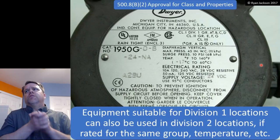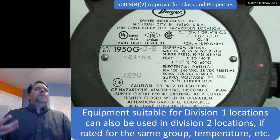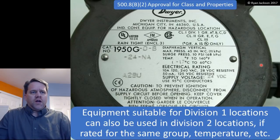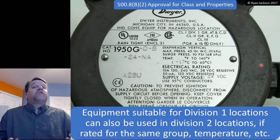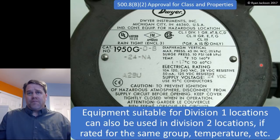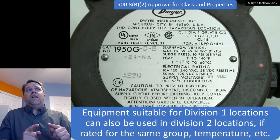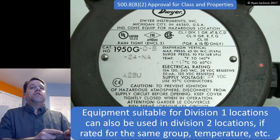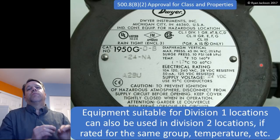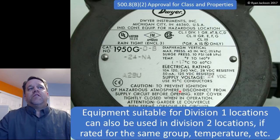I know some people look at it and say, "Well, man, explosion-proof equipment, that's the creme de la creme, and there's nothing worse than a flammable gas explosion." No, a combustible dust explosion can level a building easily. So it's not that a flammable gas is more hazardous, it's just a different hazard, right? So we need to protect against the specific hazard. So again, equipment that's suitable for Division 1 can also be used in Division 2.